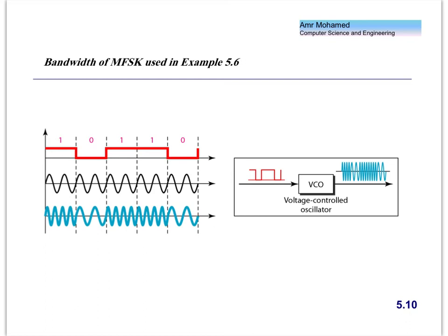So what is the implementation for the FSK or binary FSK? The implementation here is that, as I said, we can just use 2 ASK signals and superimpose them on each other. So we use 2 different ASK signals, one at F1 and another one at F2, and then we combine them together. In that case, what we do is create a digital signal that looks like this. A low amplitude means 0, a high amplitude means 1.